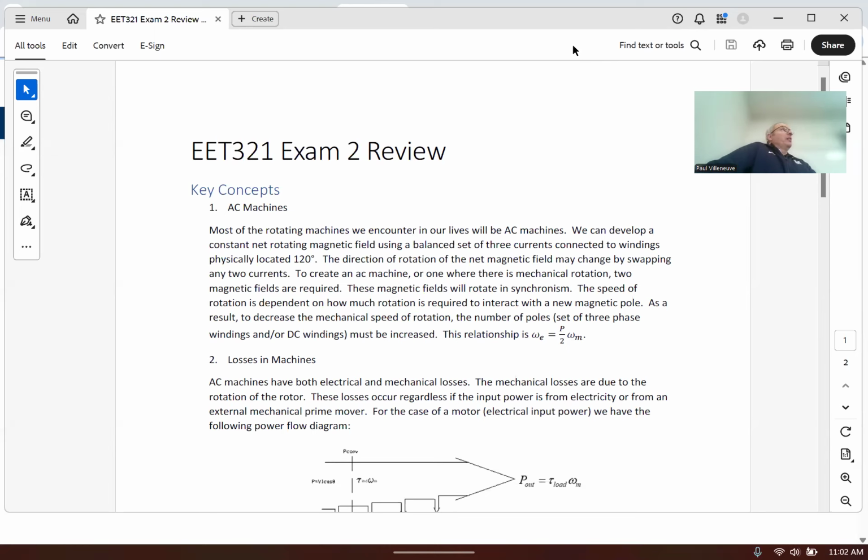When you build an AC machine, usually the stator is the more power, where the more current comes in or out of, and you locate the windings on those to have electrical separation of about 120 degrees. Not mechanical, but electrical separation. So you physically build a machine, so where the windings are, you're separated by 120 degrees. All right. Now, 120 electrical degrees is different than mechanical degrees because mechanical is based on north and south magnetic poles. So whenever you start at a north and go to another north, including the original north, the one that you got back to, that is a mechanical operation.